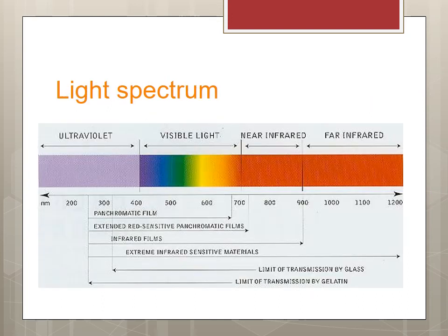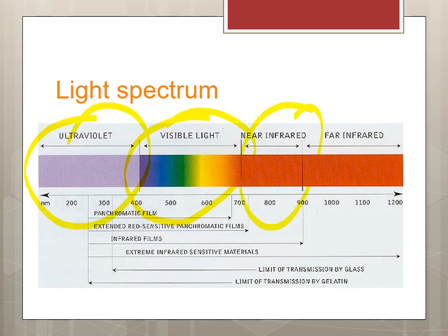So we talked again about the light spectrum. We have here our visible light that you see from a light bulb, ultraviolet and infrared, as you can see. Different kinds of infrared, and when you have flame, actually you'll have all of these light spectrums: infrared and also ultraviolet and visible light. However, depending on the intensity of the flame and what fuel you're burning, you might have different colors, so we want to detect all light spectrums.